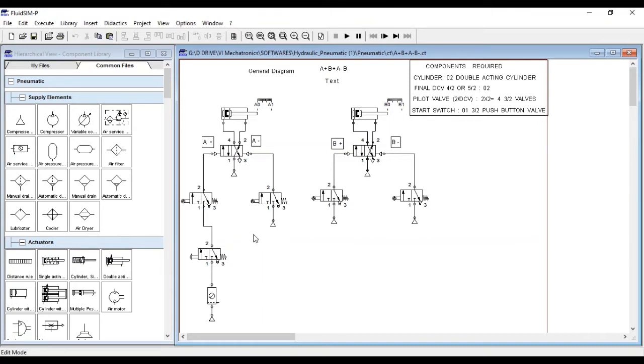Now, how to decide which are these valves? That is the trick, which is very important, that I am going to share with you. These two valves have two pilots, so two pilots have two roller switches. So how many valves? Two valves, two pilot switches. So in total we want four switches, that are nothing but 3x2 roller valves. 3x2 roller spring return. This means once this roller switch is released, it should regain its original position. Now, this is to start.